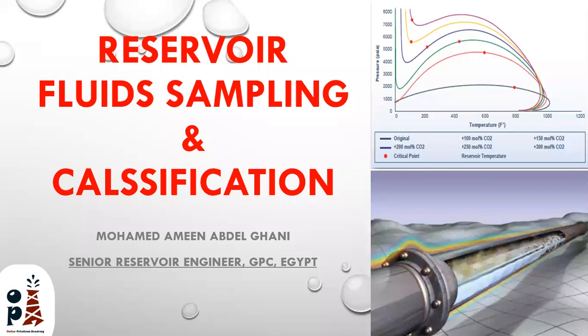There's another question. When do we use CGR? The CGR is for condensate gas ratio for the yield or the RV. All these terms are for the associated oil with the separated gas for the gas production. What is the amount of oil that is associated with the gas production, and it is measured in standard oil barrels per million standard cubic feet.